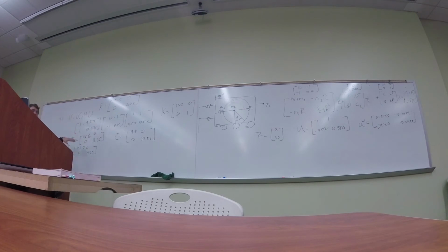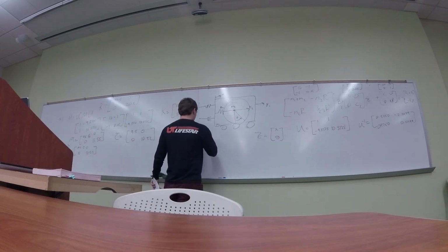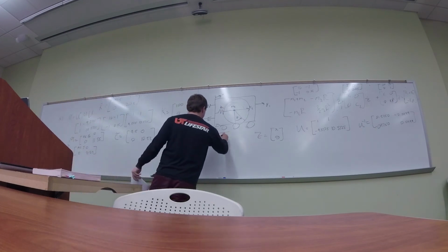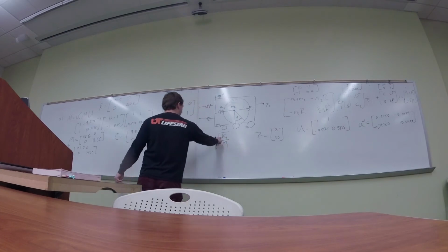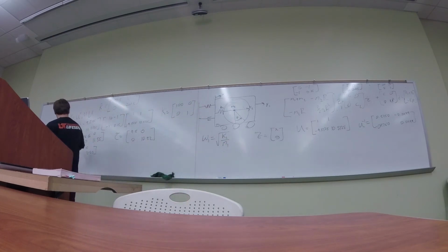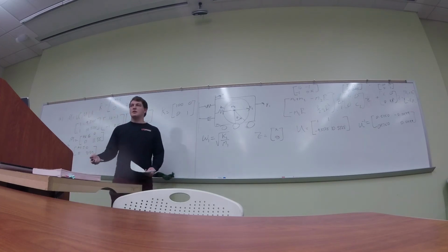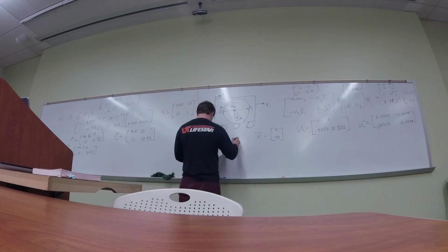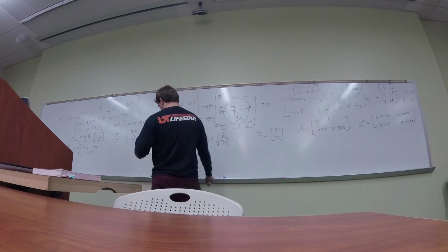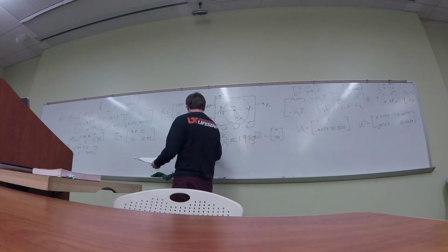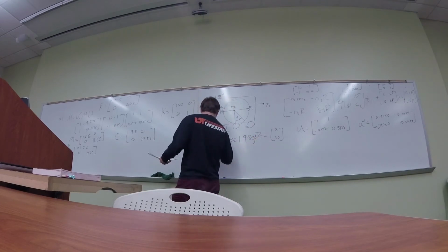And this is for the first mode. So if I'm trying to find my first natural frequency, what is the equation of natural frequency? Square root of K over M. So for my first one, I look at K1 and M1. That's the nice thing with this: you can literally just take this 48.6 and this 190.5, plug it in, and you'll find that it's roughly 1.98 radians per second.